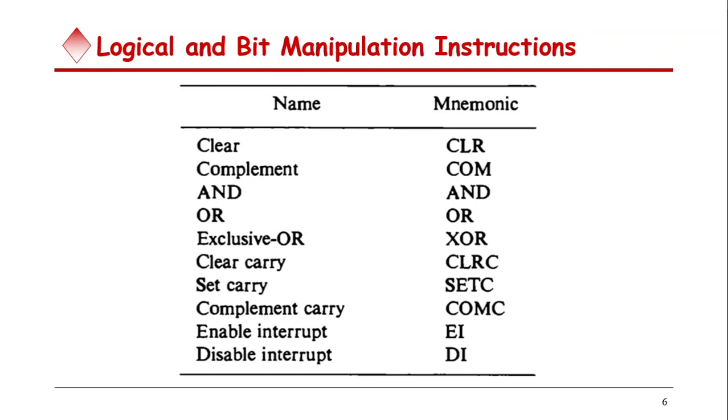That means a binary variable ORed with 1 produces a 1, but the variable does not change when ORed with 0. Therefore, the OR instruction can be used to selectively set bits of an operand by ORing it with another operand with ones in the bit positions that must be set to 1.